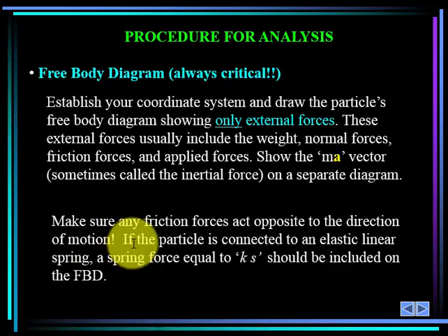Friction never assists the body in moving, and so it opposes relative motion between two surfaces that might be rubbing together. We might also have particles that are connected to linear springs. Make sure you place any spring forces on there. Make note that those spring forces would be a k value times some sort of displacement value.